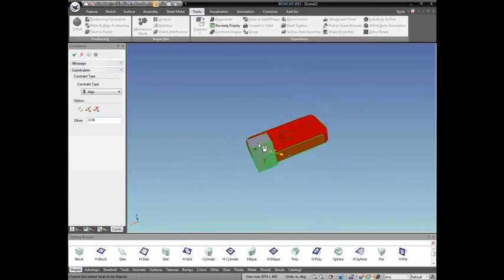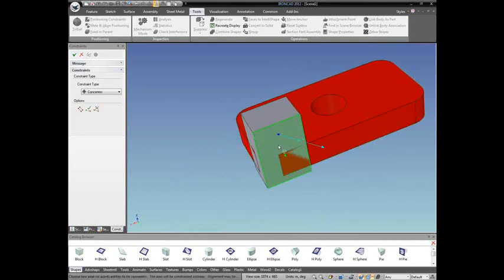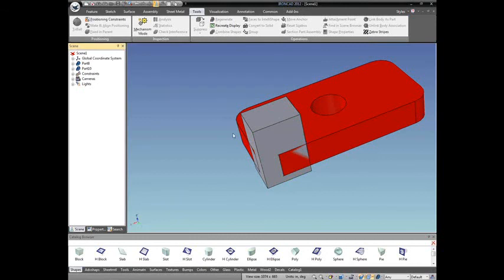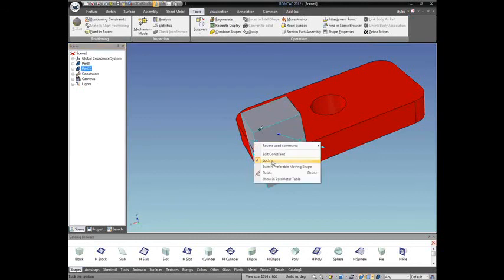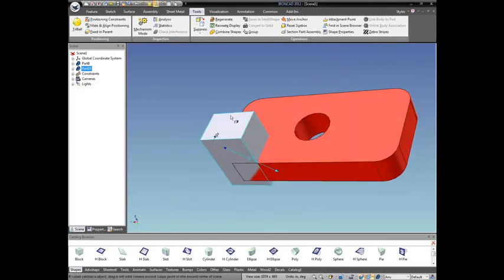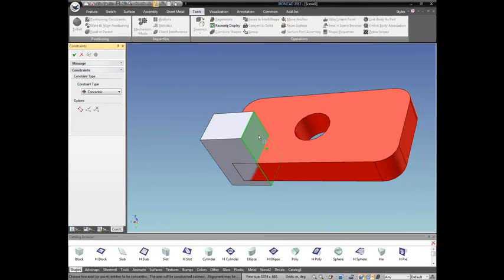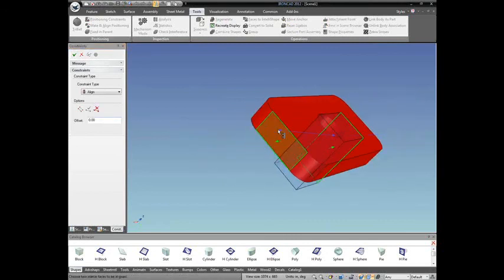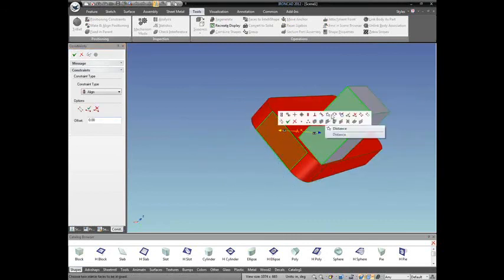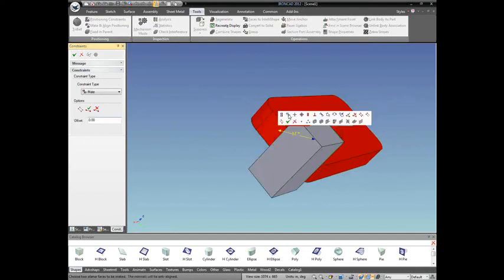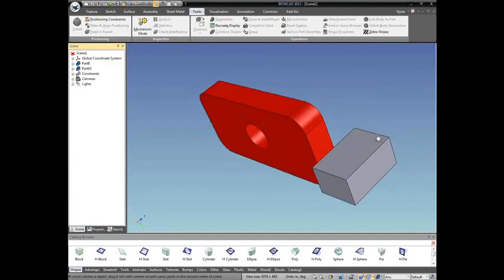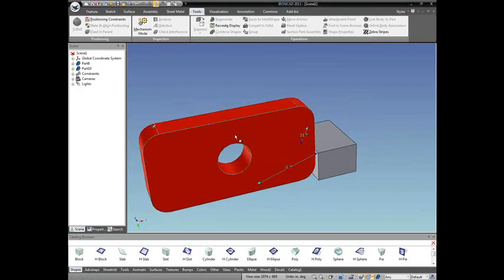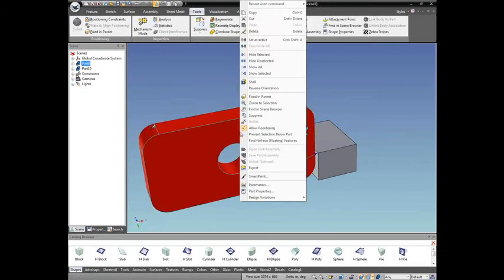You know what? I think we should have a lesson in constraining too. Yeah. I'll tell you what, next time we'll do constraints, because 3D constraints are definitely tricky. I mean, I got myself mixed up. I did an align instead of a mate. It's an easy mistake to make when you're going through these, and you just miss a click. I've been so confused on that sometimes, not knowing what to do. Yeah, no, absolutely. That's a good idea, Joe.